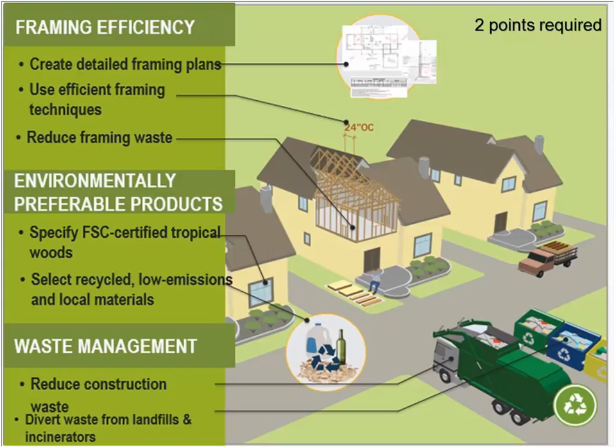So also, this is the section where you have more sustainable materials, so recycled content in your aggregate, in your walls, in your framing, in your drywall. Having your materials come within 500 miles, being mined, manufactured, you can pick up some extra points here. And then also having low emitting materials, which is getting moved to the health section in V4. That's also important, and it will spell out which, like your low emission paint or no VOC paint credits are in this section. And then last but not least, you do have to investigate waste reduction opportunities. They just ask that you at least investigate it as a requirement.